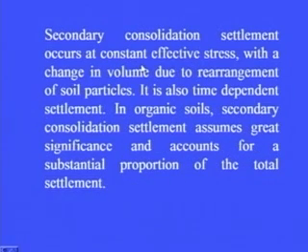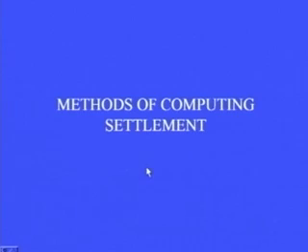Secondary consolidation settlement occurs at a constant effective stress with a change in volume due to rearrangement of soil particles. It is also a time dependent settlement. In organic soils, secondary consolidation settlement assumes great significance and accounts for a substantial proportion of the total settlement.